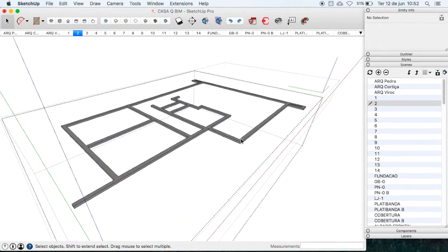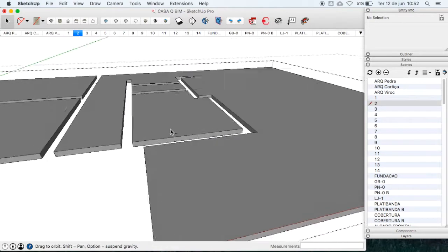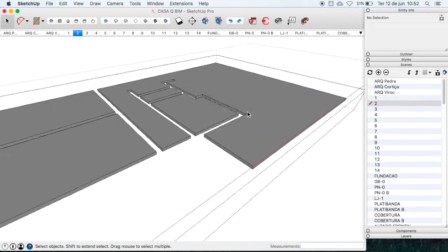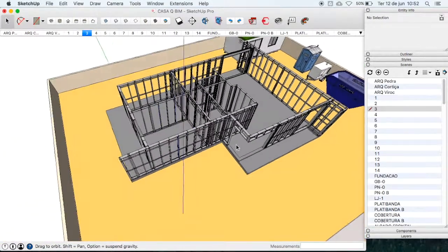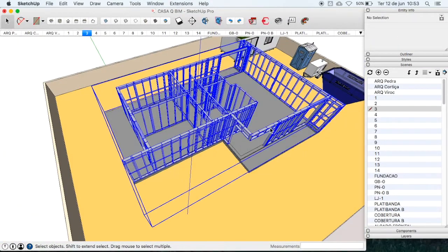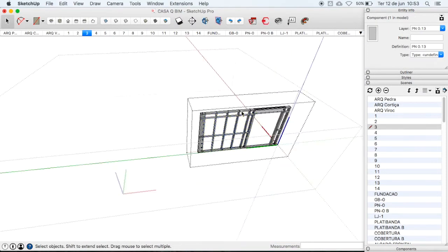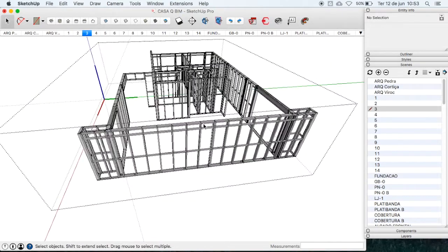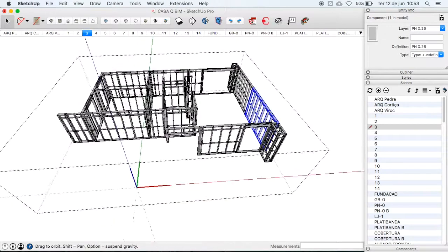This allows the use of 3D models to generate the final drawings, the 4D planning, and the extraction of quantity of each material. You can see that the light gauge steel frame structure is all divided by panels, because this is the way it will be fabricated and assembled. All the elements have been identified, thinking about the extraction of the list of materials and services.